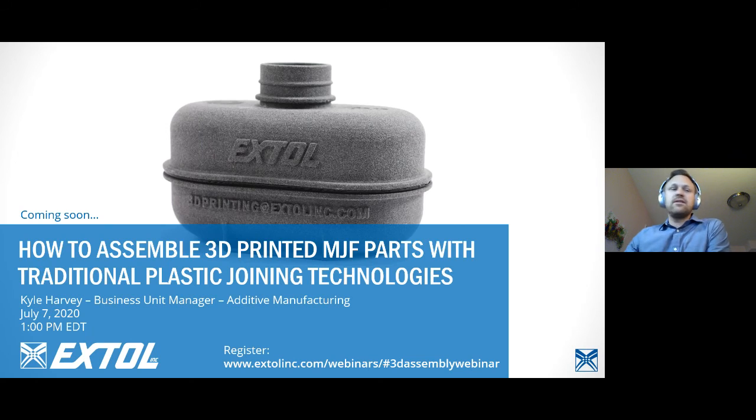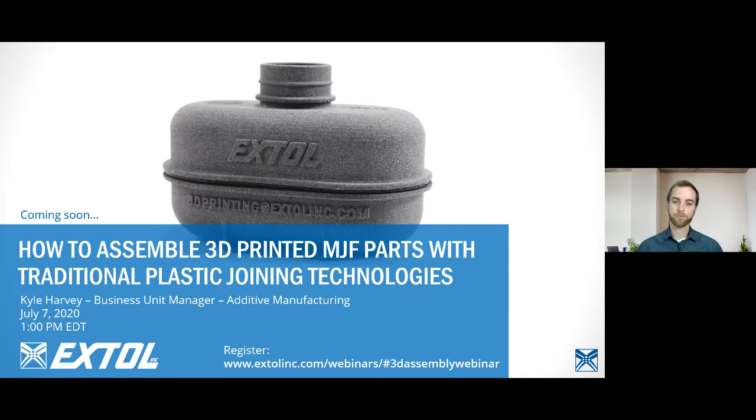The first one that we have is, can you print these two materials at the same time, or can you print two materials in one part? Yeah, I get that question a lot. Unfortunately, no. With the powder-based system, we're limited to one powder at a time, but we can print them in two different printers in parallel, and then put the two parts together afterwards.